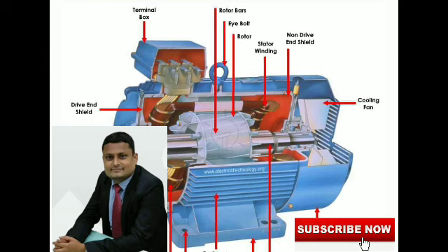Please keep noting, I will be going very fast. ZS is conductors per slot, KS is the slot space factor. We write KS equals copper area by total slot area, which should be between 0.25 and 0.4. HV machines have lower KS due to more insulation.